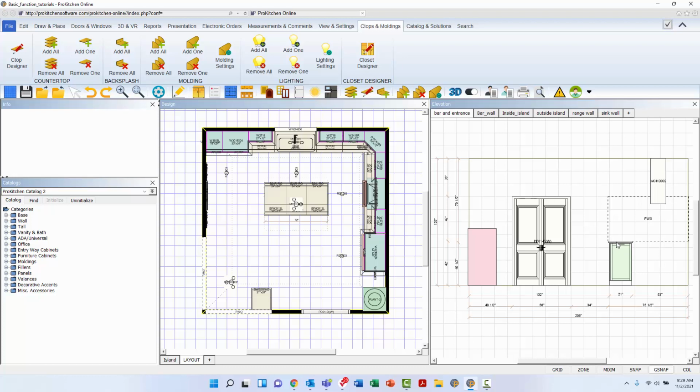When selecting the Up-Down tool in the elevation view, you may either move the countertop up or down along the wall manually with the mouse and left-click to secure, or utilize the top or bottom fields in the info panel to the left. Additionally, in the elevation view, you may move the countertop up or down without activating the right-click toolbox. To do this, left-click to select the countertop. Then, either left-click the up and down handle and move the countertop manually with the mouse and left-click to secure, or utilize the top-bottom fields in the info panel to the left.